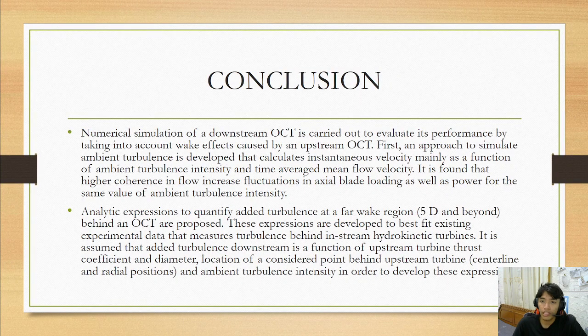Okay, so for the conclusion of this research, numerical simulation of a downstream OCT is carried out to evaluate its performance by taking into account wake effects caused by an upstream OCT. And the next one is analytic expressions to quantify added turbulence at a far wake region, 5D and beyond, behind an OCT are proposed. These expressions are developed to best fit existing experimental data that measures turbulence behind in-stream hydrokinetic turbines.